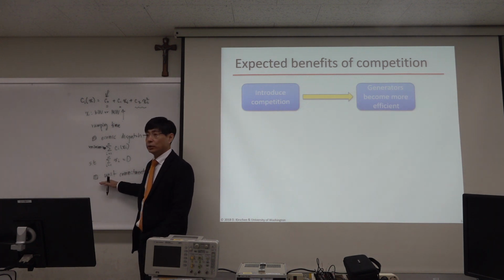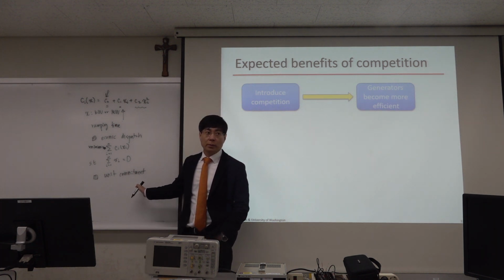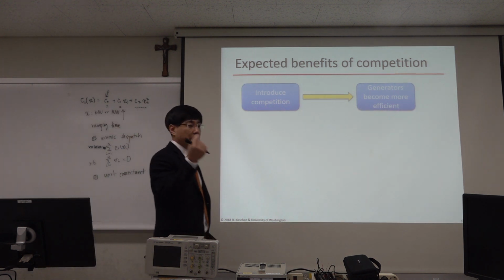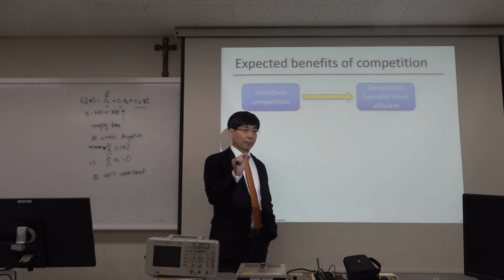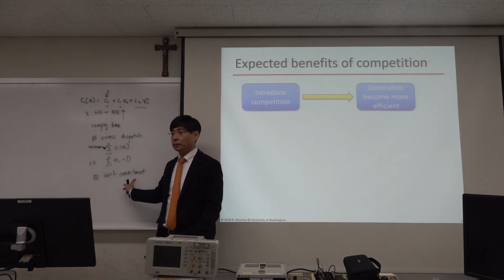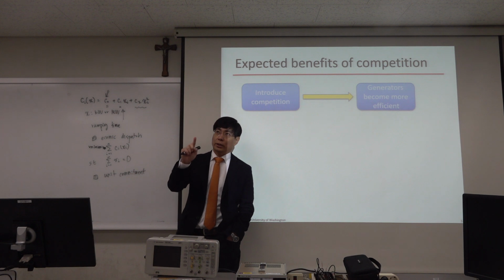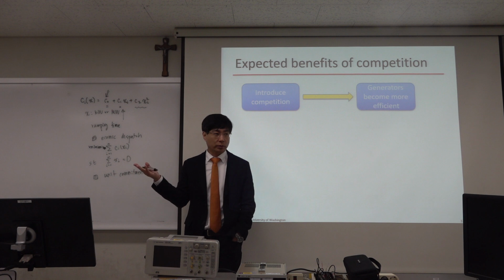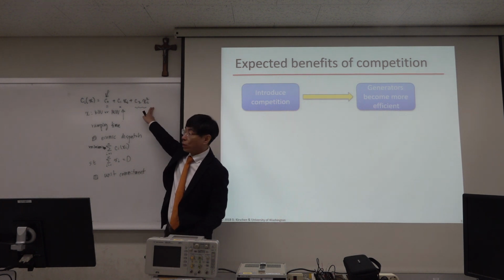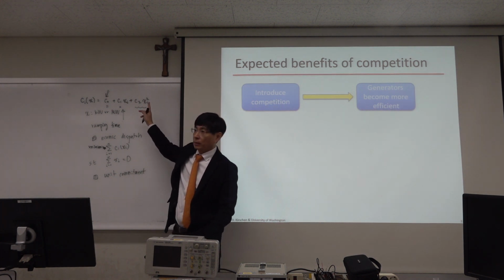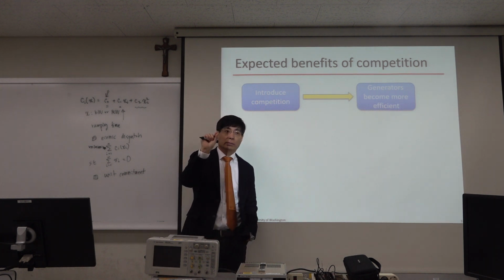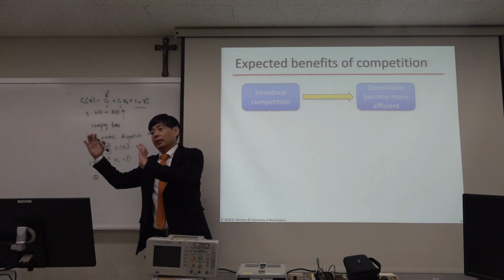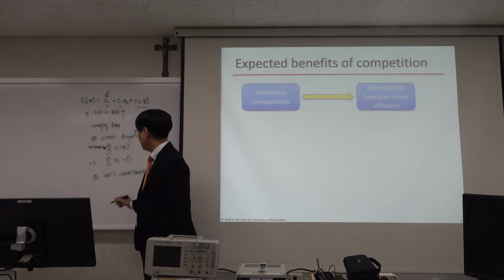Here, this unit means generators. So in the unit commitment problem, we also need to determine the amount of power to generate, but also which generators to turn on. So this is a mixed integer nonlinear programming, because this is a quadratic function, not a linear function, but it has a binary decision variable.